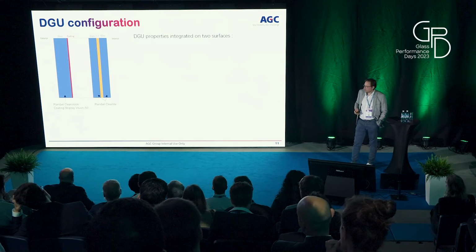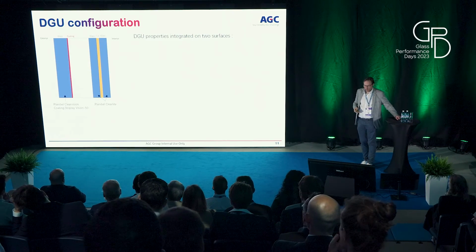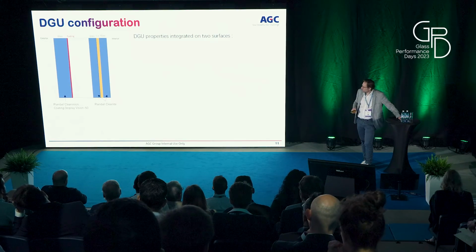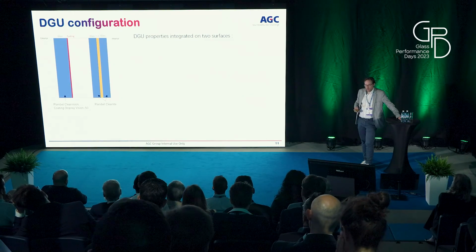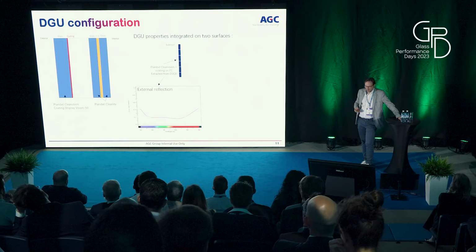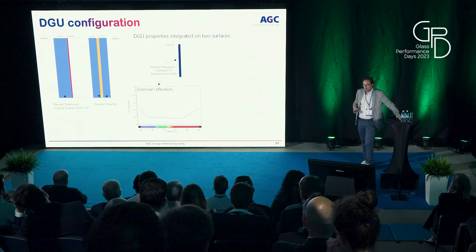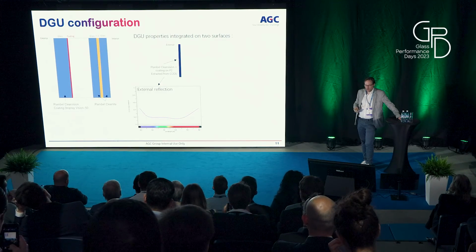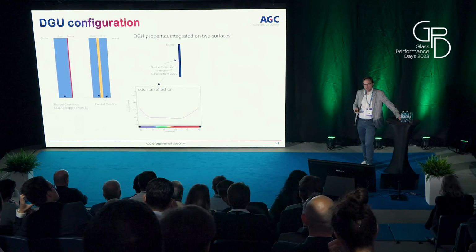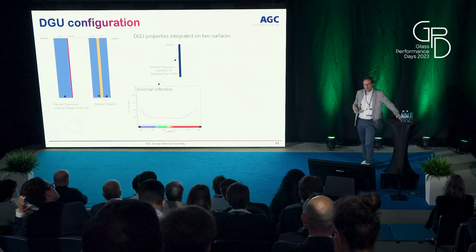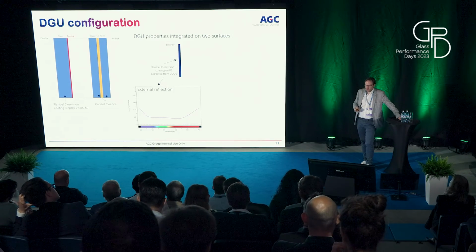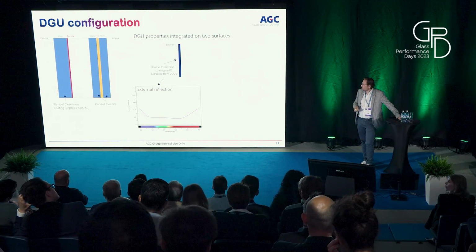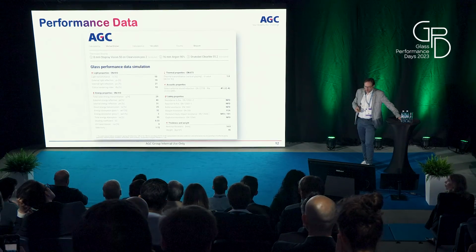As I said before, we have a double glaze unit. Outside glass is a tempered glass, 8 mm, with a coating, low iron glass, and the inner light is a laminated safety glass with a PVB interlayer. So we need the spectral data, because this kind of simulation is a virtual prototyping, virtual rendering, which is based on real spectral data, which means data per wavelength. It's not integrated; it's using really spectral data and then integrating the data, not using integral data from the beginning. And the overall data are displayed here.